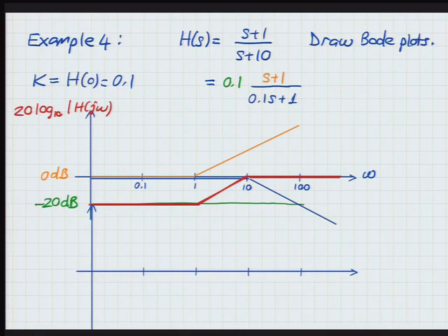All right, so for the phase, we're looking at the gain first, and the gain contributes nothing, right? The gain is positive, so the phase of a positive number is 0, so 0 degrees for the gain. So I don't even need to draw this, but just to be complete. So that's 0 degrees. What about the zero? It's going to contribute eventually an angle of positive or negative? Positive 90 degrees.